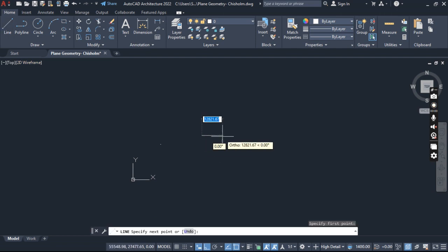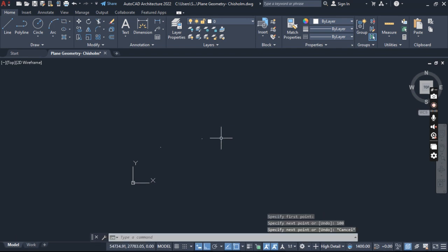If I click the line here, click line command, what I did, I zoom in. No, I zoom out a little. And the value that I'm seeing is 12,007.60. If I type 100 here and I press enter and press escape, I'm seeing a little dot. That's because the line that I'm drawing is only 100 and the value that I was seeing is 12,000 something. All right, so you have to ensure that you can see a value close to what you're drawing, or else you're gonna be wondering where is the line.